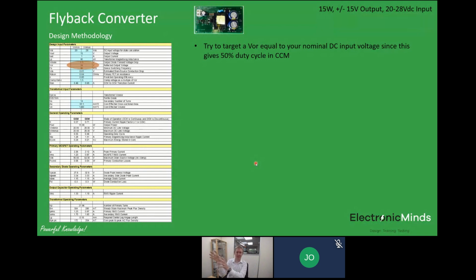Now, if we operate at an extreme of duty cycle, say 10%, it means that the RMS currents in the system on either one side or the other are going to be very distorted. So you'd end up pushing a lot of loss onto the primary or onto the secondary side. So if you can sit at a target of about 50% duty cycle, you nicely balance the stress on the two sides of that circuit.